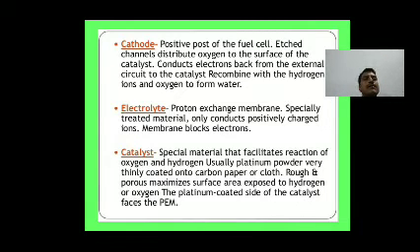Cathode. Positive post of the fuel cell, attached channels distribute oxygen to the surface of the catalyst. Conducts electrons back from the external circuit to the catalyst, where they recombine with the hydrogen ions and oxygen to form water.